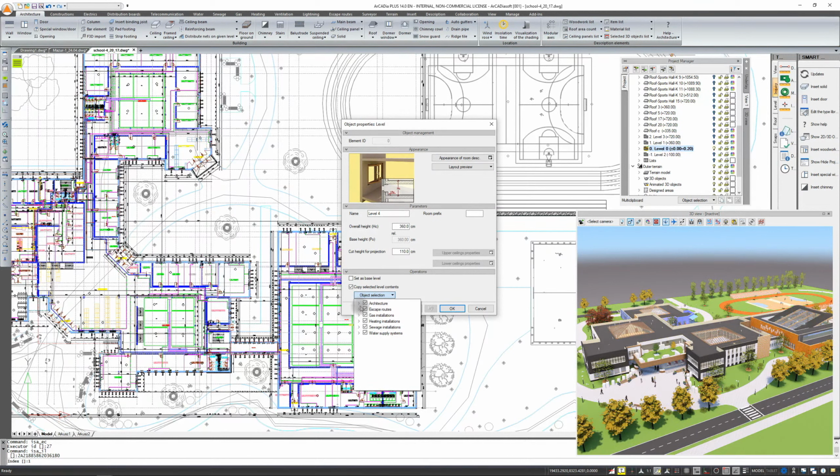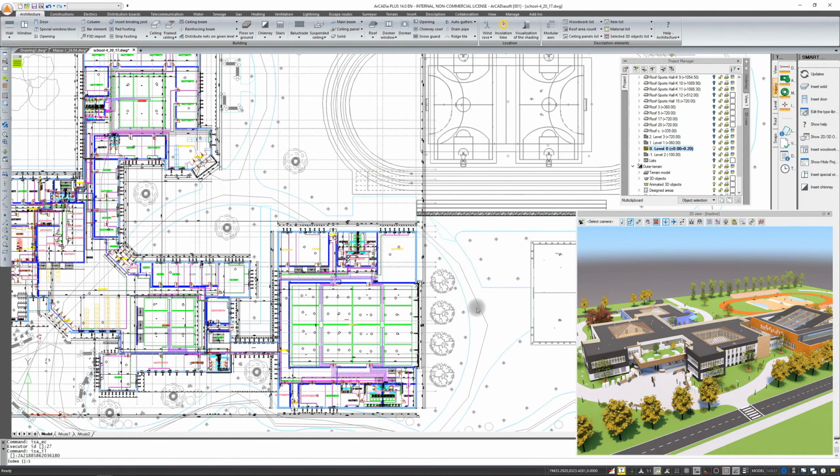And now, if we have several industries in a given project, absolutely all of them will be shown, but we can only use one. Or we can copy, for example, only walls. It is up to us to choose. If we do not want to copy anything, of course, the marked level will be created and we can draw it from scratch. We still have the levels visible by default, the one below, because the program automatically switches to the new level that was created.